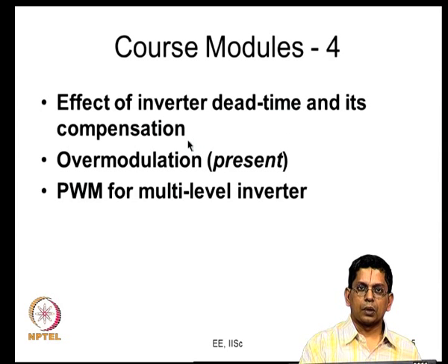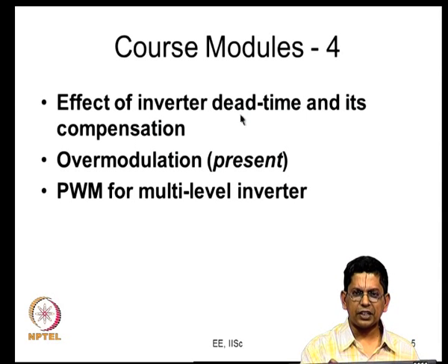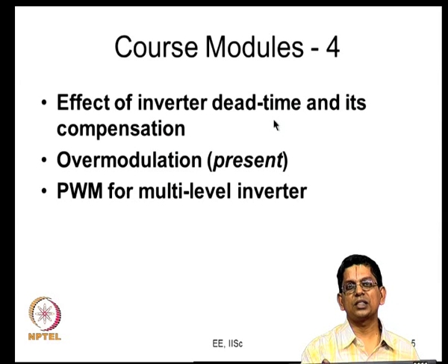So, we could do that. So, here we are going to look at something that is nonlinear. Firstly, what we found was that the effect is that the fundamental voltage is no longer proportional to the reference, because that is the ideal fundamental voltage. On top of the ideal fundamental voltage, there was a small component getting added, which is the fundamental error voltage caused by dead time, and whatever you are getting is the phasorial sum of these two, the ideal fundamental voltage and the error fundamental voltage. So, you have the phasorial sum.